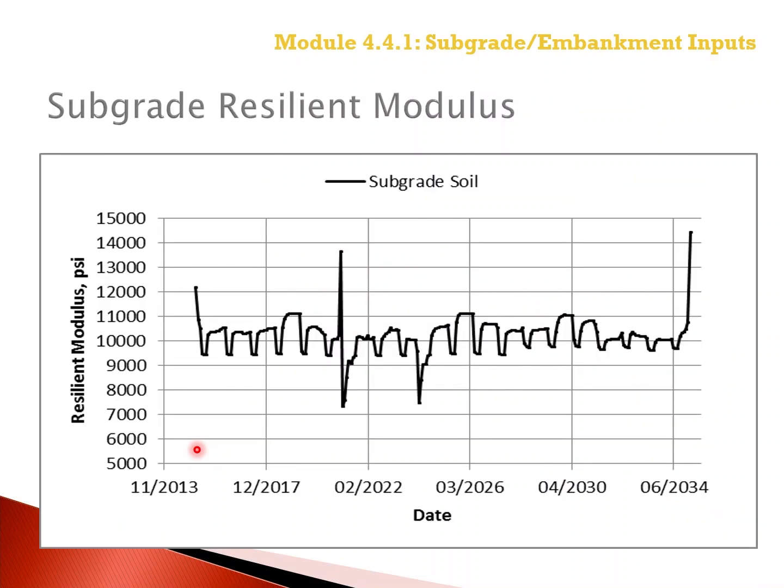The resilient modulus is entered into the Pavement ME design software basically as the starting point for the critical response calculation. The resilient modulus is determined over the design period based on the temperature and water content, or degree of saturation, calculated by the EICM and other properties of the subgrade and embankment soil. So the starting resilient modulus can be estimated from AASHTO T307 or one of the other surrogate tests for input level 2, as an example, CBR or R-value.